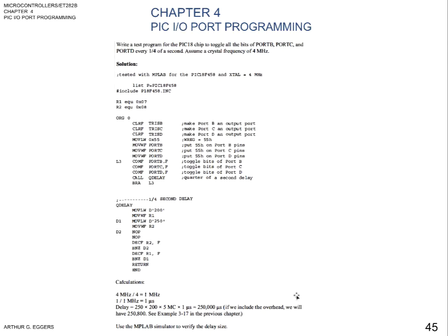You're not going to use a piece of hardware for this. You're going to use the simulator within MPLAB. So as you go through and set up a file, instead of choosing PIC 18F458, go ahead and choose your 4520 and set up your file, just like I showed you in the MPLAB X IDE tutorials. And then enter the information. Get used to entering this information and testing it, and see if it in fact works.